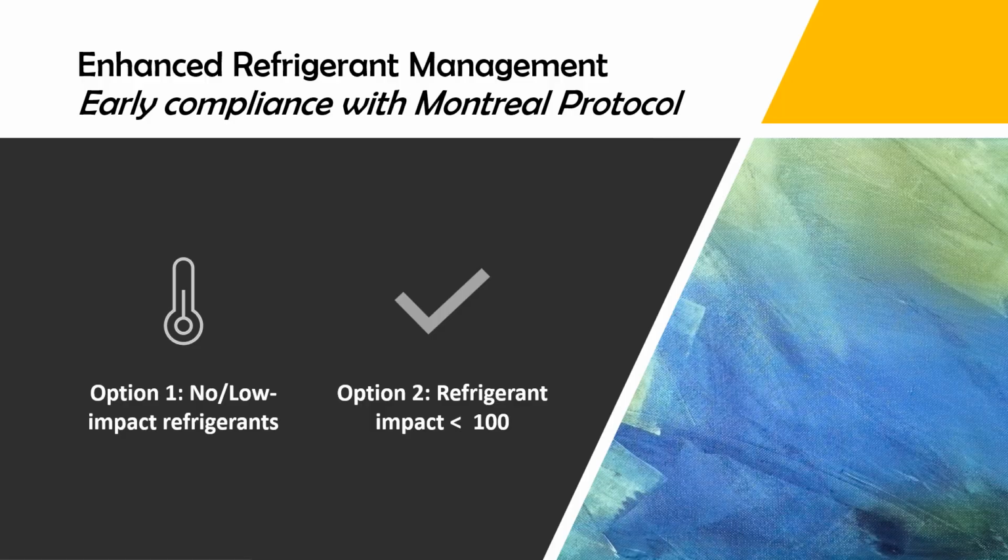Earlier we mentioned the enhanced refrigerant management or earlier compliance with the Montreal Protocol. The intent of this credit is to support early compliance with the Montreal Protocol while minimizing the direct contribution to climate change. Option 1 is to use no refrigerants or low-impact refrigerants, whether naturally occurring or synthetic, that have an ozone depletion potential of 0 and a global warming potential of less than 50. You can get 1 point for that.